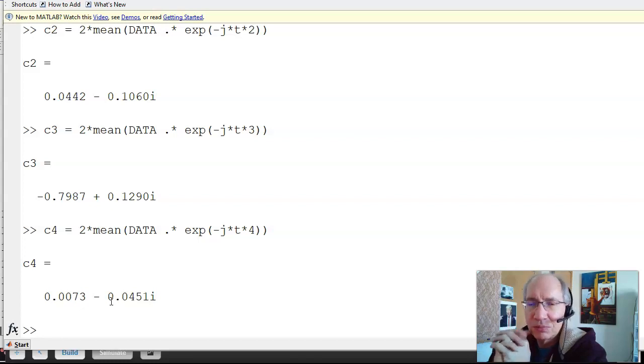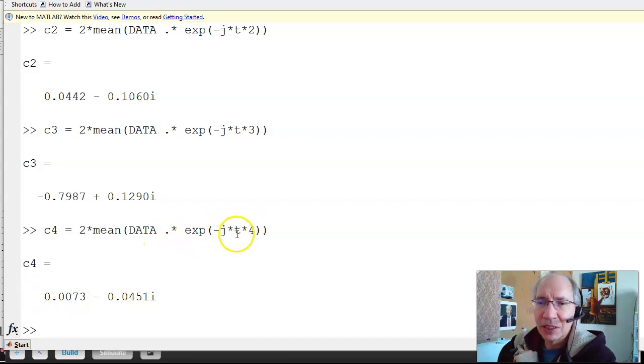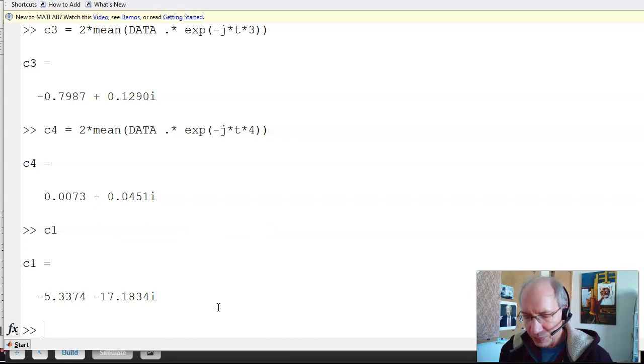It's just take your data, hit it with the sine and cosine, or if you don't mind complex exponentials, I can get sine and cosine in one shot using e to the minus j omega naught t. In terms of the energy of a sine wave, well, the peak magnitude of the sine wave is the first harmonic.